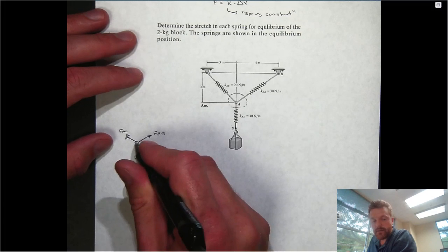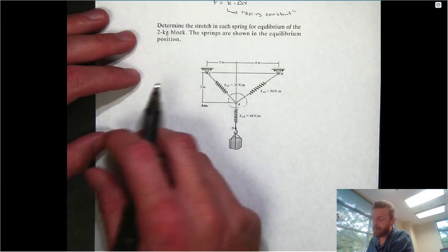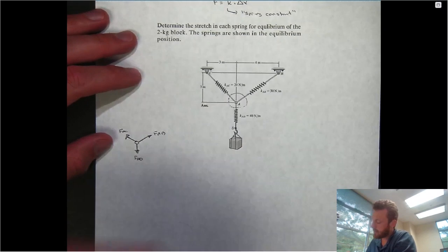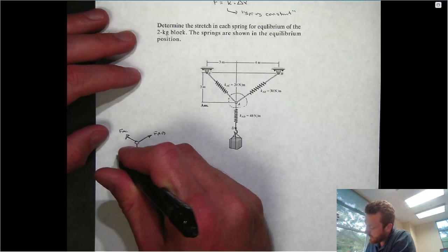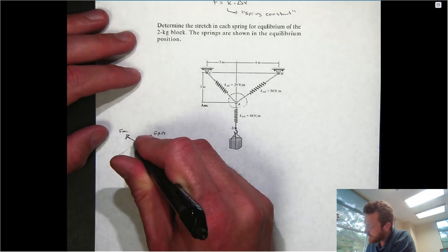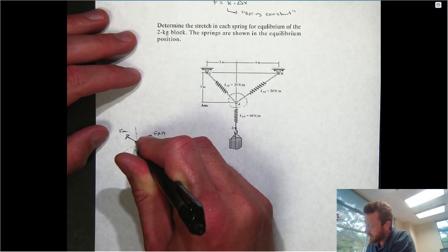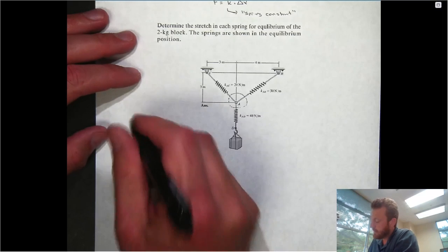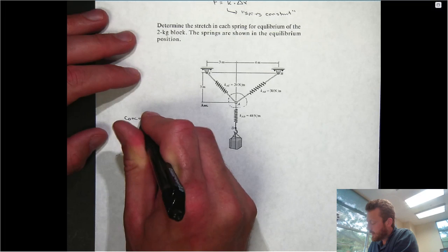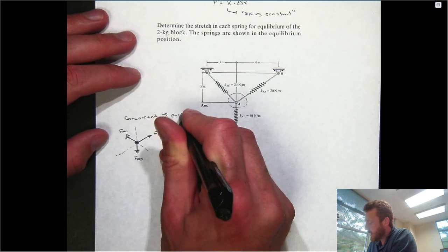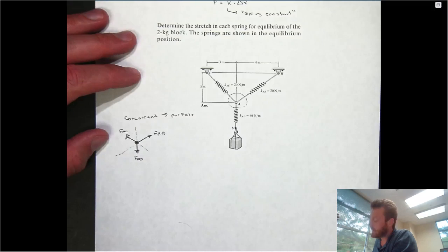Now, naturally, this O-ring has some dimensions to it, right? It's a fabricated real structure. So it might not be immediately obvious that we can model this as a particle. However, if we extend the line of actions of each of these forces, we'll note that all of their lines of actions pass through a point which is dead in the center of that O-ring. So we called those concurrent forces. And we said whenever forces were concurrent, that a particle model was a valid form of analysis.